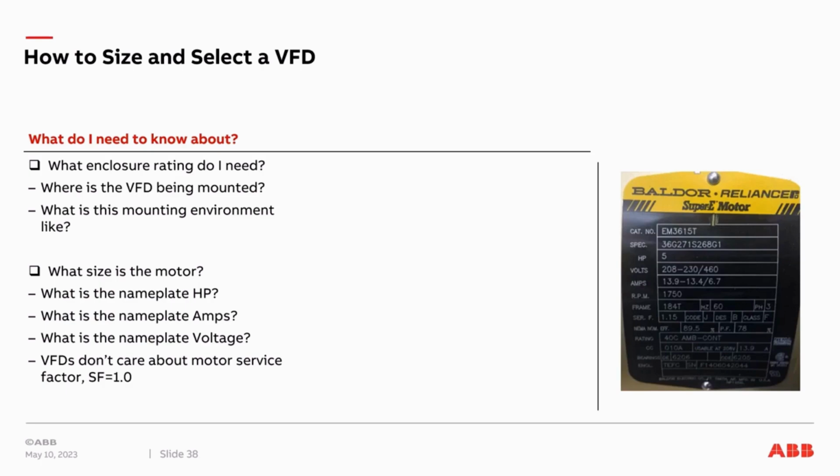By doing that, though, the expected life of the motor will drop dramatically, and the motor will run much hotter. When a motor is run by a VFD, we always consider the service factor to be 1, because the VFD's pulse width modulation that we talked about earlier actually causes more heat inside the motor. Therefore, you cannot run it beyond its service factor of 1.